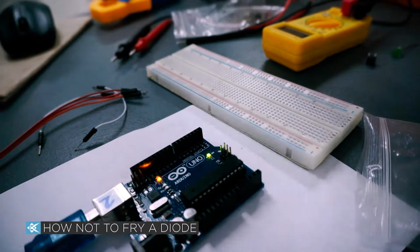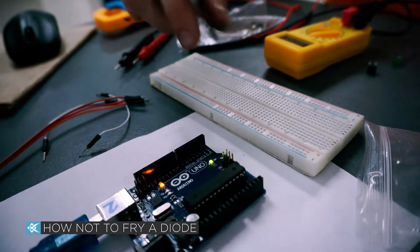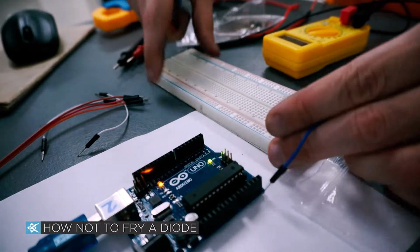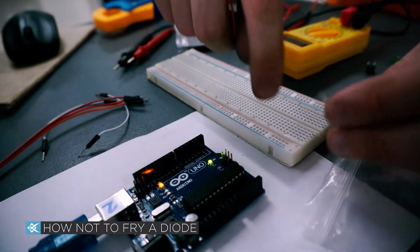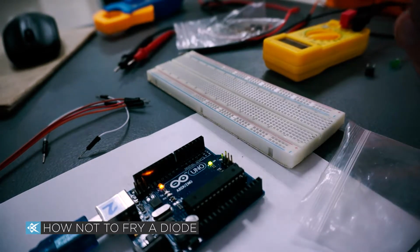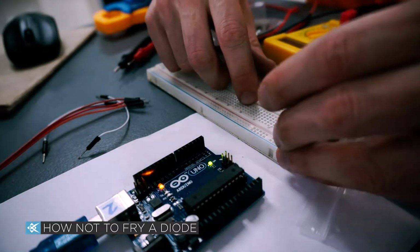And it just helps make building circuits very quick. Usually we use the bottom and top as what we call the power rails. So we put negative as the ground, and the positive is going to be your voltage, right? Usually 5 volts. So I'm going to do this.